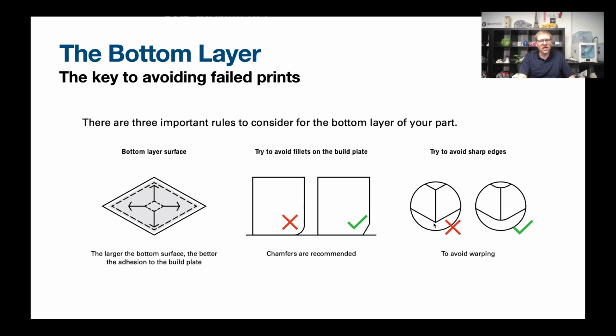On the corners, if you can, avoid sharp corners, at least, again, where it's on the bed. So think about where it's printing that base layer. Try to avoid having it do sharp corners on that base layer. If you can have a little bit of a rounded corner so that the print head goes around the corner instead of hitting a point and then turning direction, it's going to be less likely to peel up off the bed at that corner. So having a curved corner is helpful for that first layer.